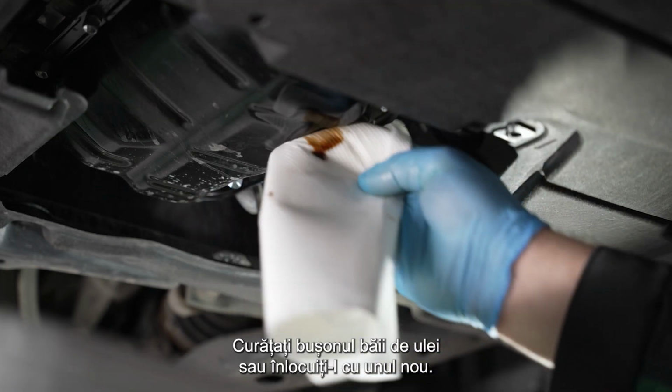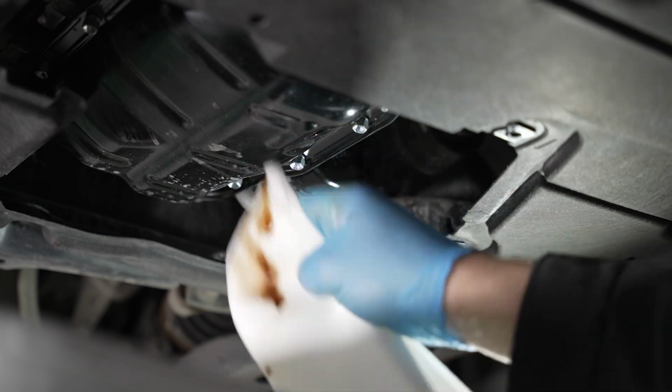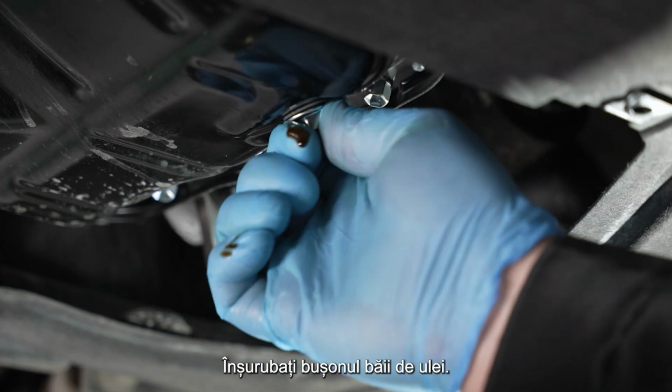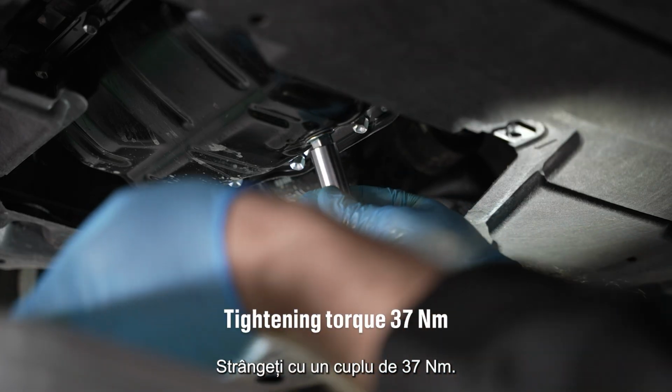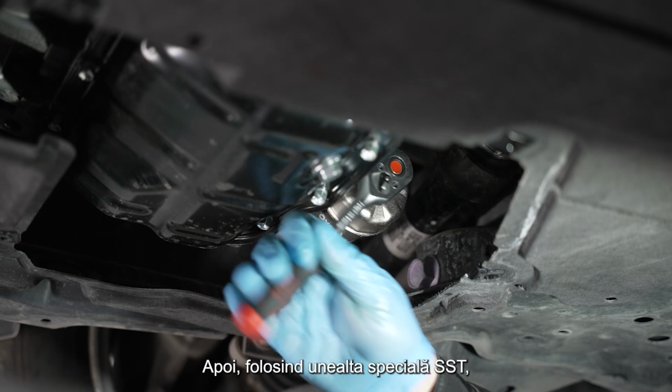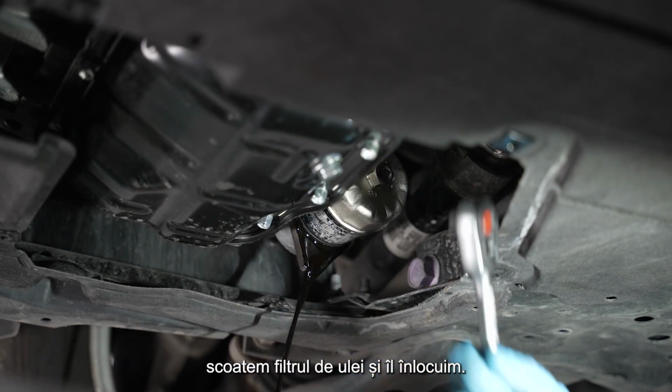Clean the oil sump drain plug or replace with a new one. Install a new gasket on the oil sump drain plug. Screw in the oil sump drain plug. Tighten with the torque of 37 Newton meters. Next, using the SST special tool, we remove the oil filter and replace it.